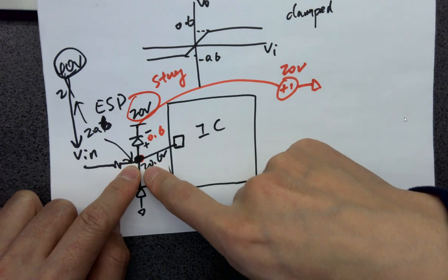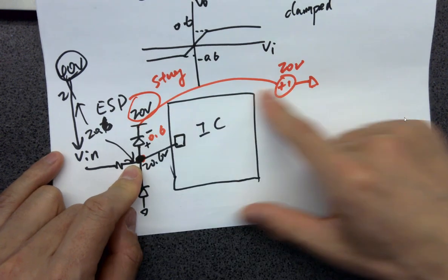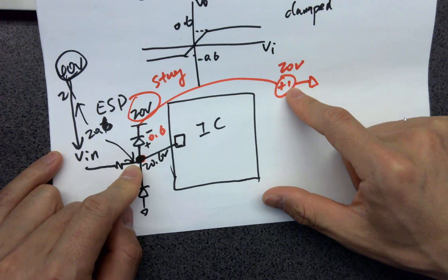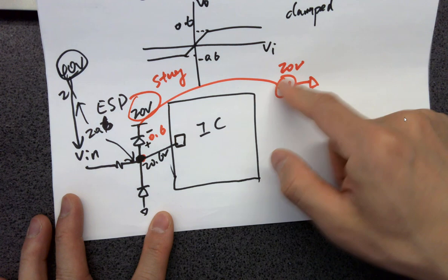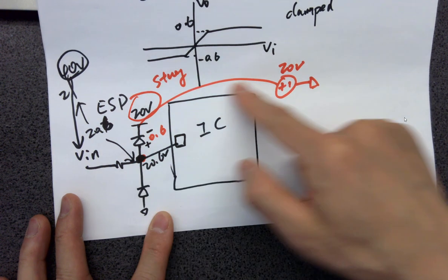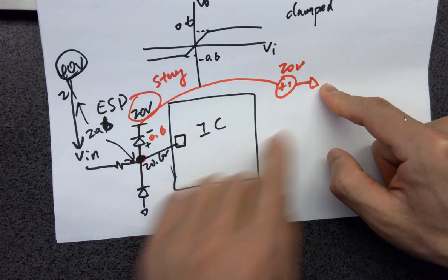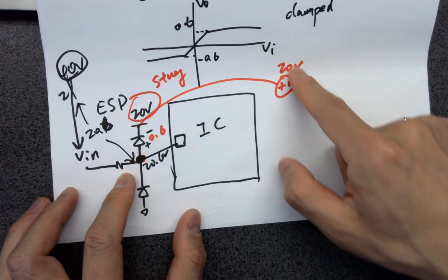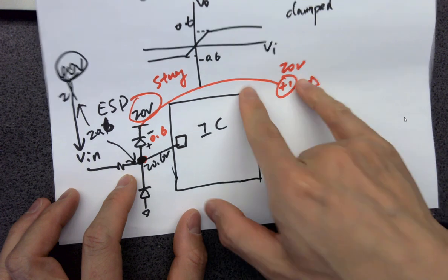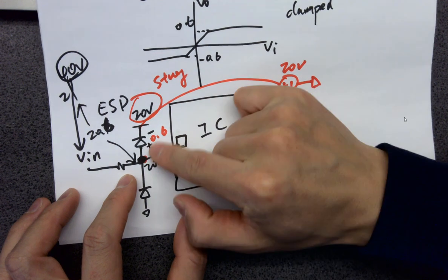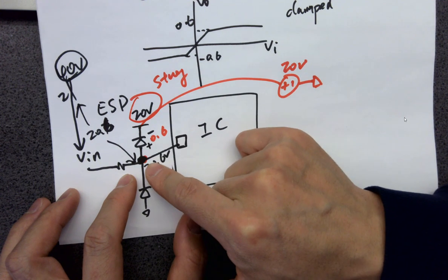And you're asking why it knows that it has to be at 20.6 volts. It's because you have a really powerful DC power supply, which has zero internal resistance. So that's why it allows current to go into that power supply, going this way. It eventually flows through that power supply and reaches the ground, which is fine, okay? And because we know this is an ideal power supply of 20 volts, it's dropping 20 volts from here to ground. And we know this is fixed as well. It's dropping 0.6 volts. So eventually this node has to be 20.6 volts. There's no other choice.